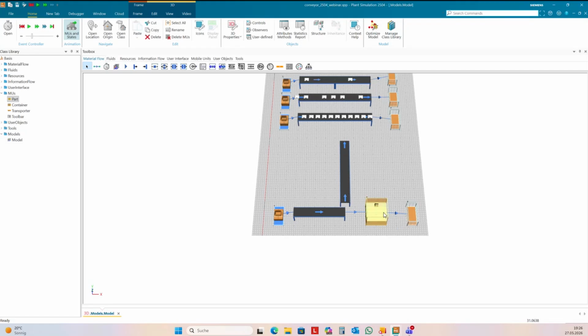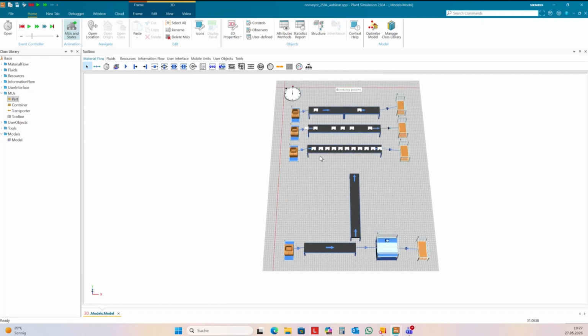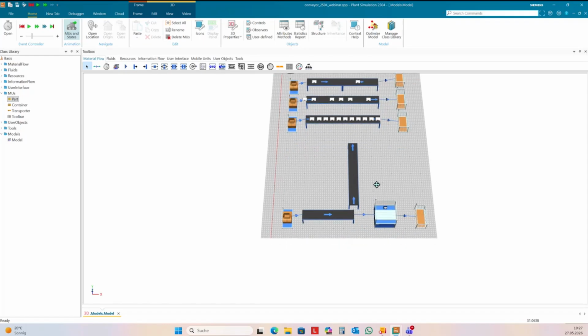And if here at the station exit there are some parts on conveyor 6 and no parts on conveyor 5, this part should go out from this conveyor and go inside the machine. What we need is the same behavior I showed you here. For piling up, I need a gap of 0. Then it piles up. And then for going out, I need to switch the conveyor to backwards, and then I need a minimum gap of -1. And then it's able to run out of this conveyor. So I need some controls for this. I need the exit control here.